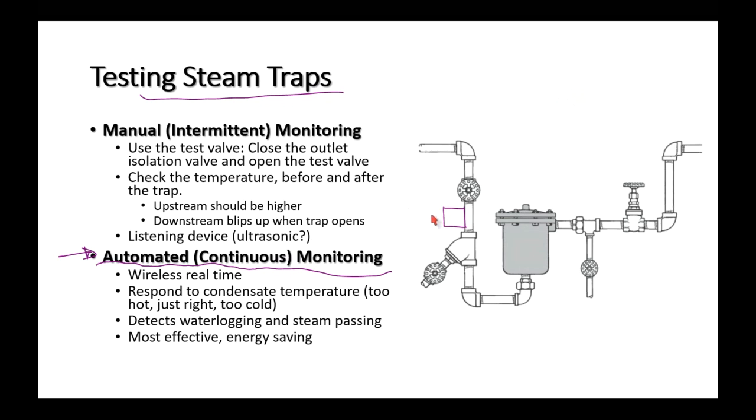So in other words, what we have is a cold junction, and we've got a hot junction, like a thermocouple. That's how a thermocouple works, and it generates its own electricity based upon the difference between the ambient air and the temperature of the steam in the pipe. So that is number one, really, really cool. We don't got to replace batteries. We don't need a power supply, nothing.